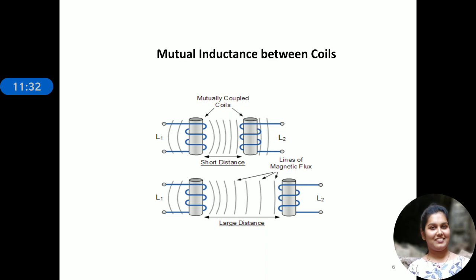If the two coils are tightly wound one on top of the other over a common soft iron core, unity coupling is said to exist between them, as any losses due to the leakage of the flux will be extremely small.